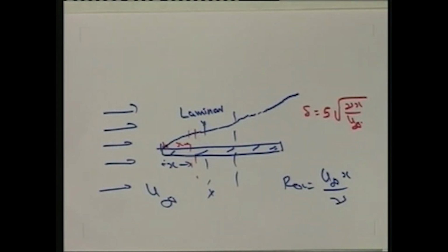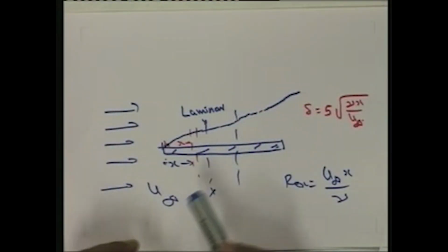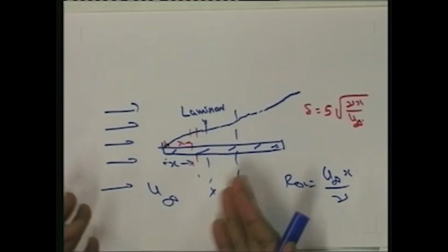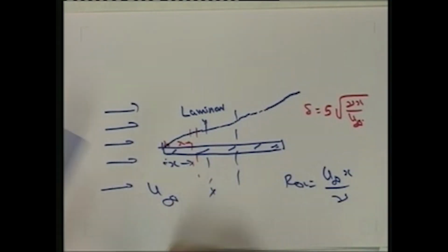So, this relationship derived by Blasius through various experiments we can utilize, and then if you define a critical Reynolds number from which onwards the flow is transition or turbulence, then we can put that condition. So, the boundary layer thickness delta, with respect to the figure here, as we have already shown. With respect to the boundary layer, various characteristics for this laminar boundary layer can be obtained. The various characteristics are defined here.